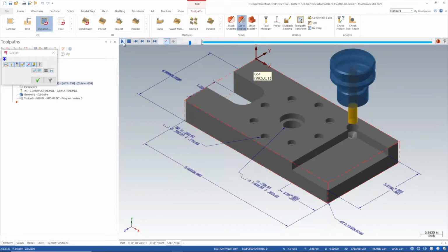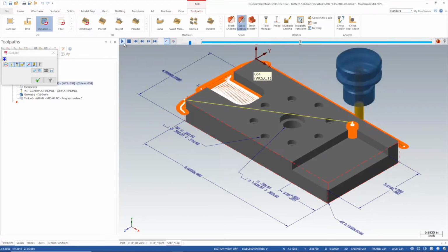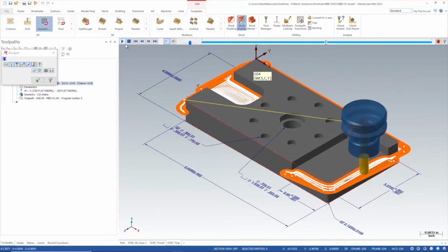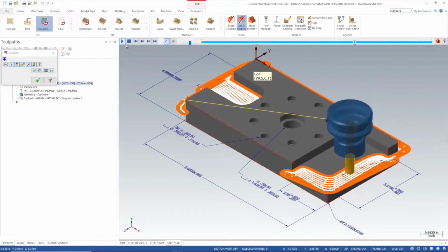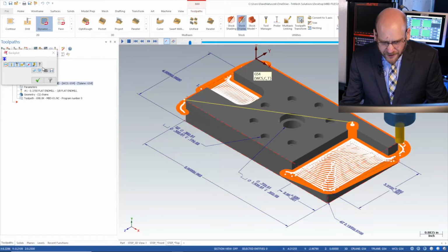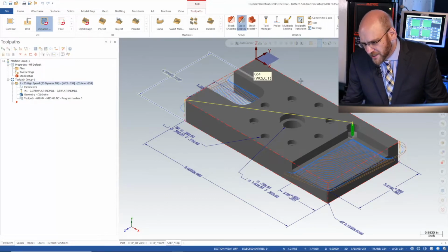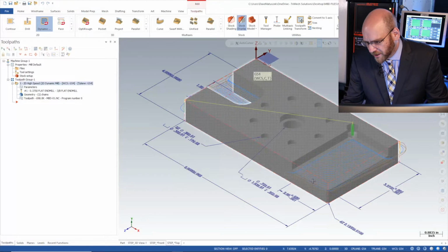So here we go. We now have this part toolpath. Yeah, that's a really great feature to have, maintaining a constant chip load on the tool. That gets rid of any of the manual calculations that somebody might do in order to get there. And now what we can do is let's use some of our MBD data to maybe machine these, use different strategies on the different walls.